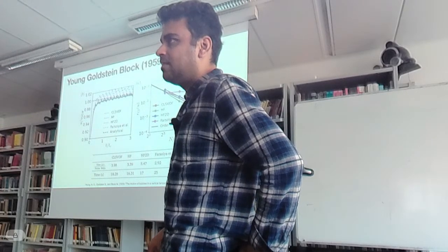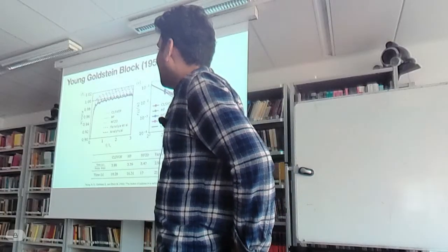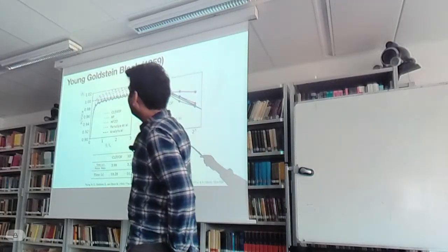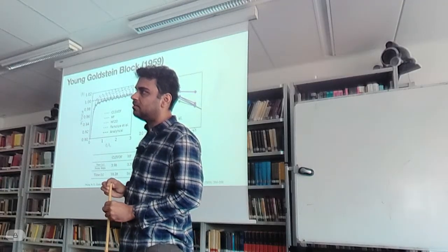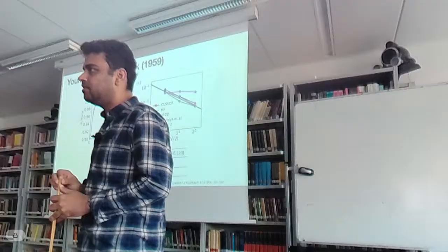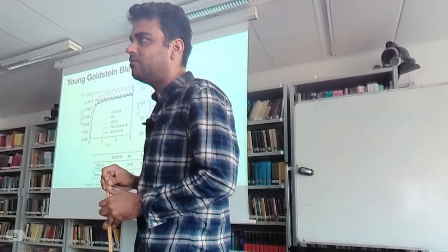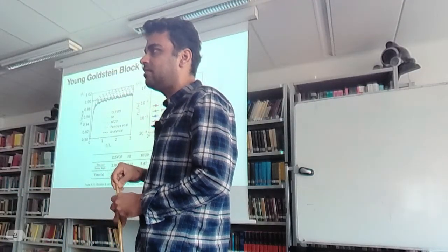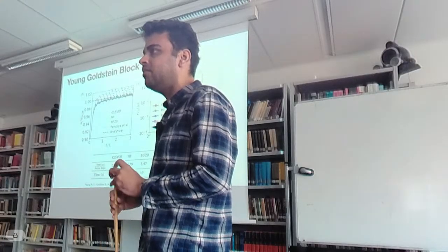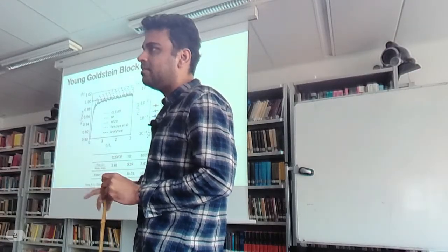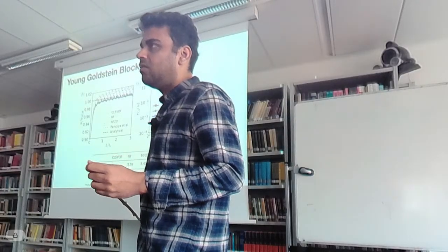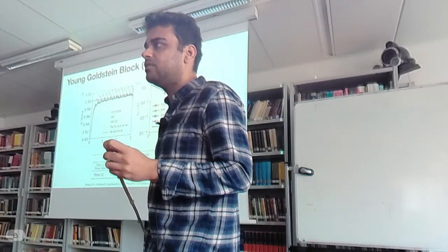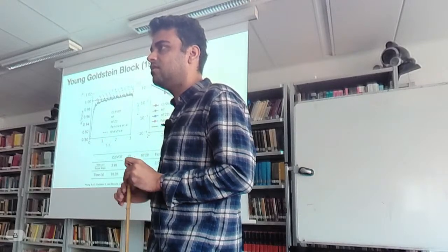I think it's because he's not putting the correct surface tension force that should be there. Basically he's not putting the correct force, which is related to how he calculates this using either the surface gradient of the surface tension or the way you add forces in the CSF formulation.